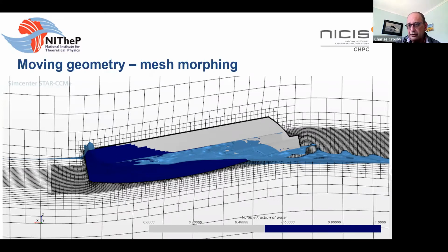By the way, negative volumes are a feature of meshing for CFD. Typically, when you're dealing with structured meshing, it's quite easy to twist or fold the grid. And you can spend a lot of time chasing down those regions of negative volume because the volume is computed from cross products of the corners.